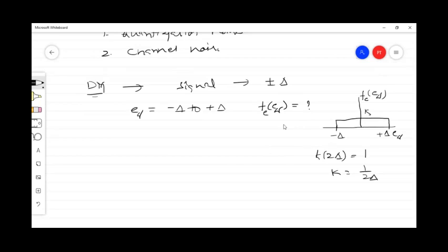All these things we already discussed with respect to PCM. Okay. So therefore, the quantization error probability density function in case of a DM signal is equal to 1 by 2 delta. Once you know the probability density function and also its range, we can evaluate its mean square value.